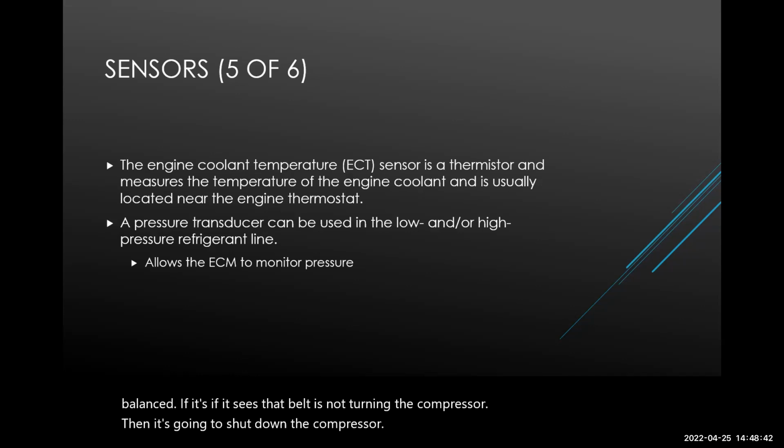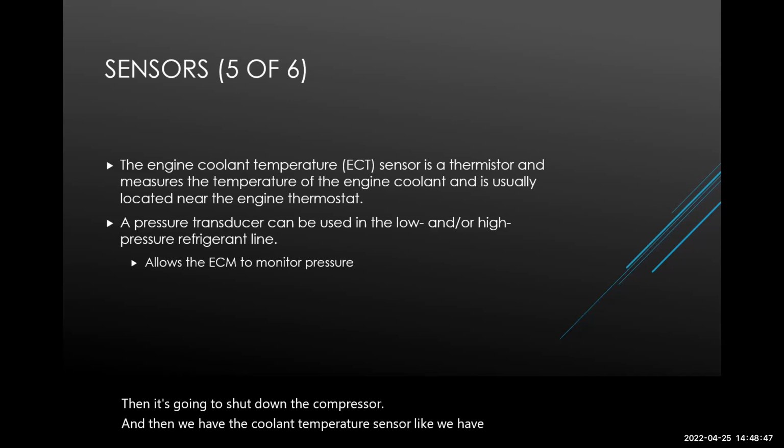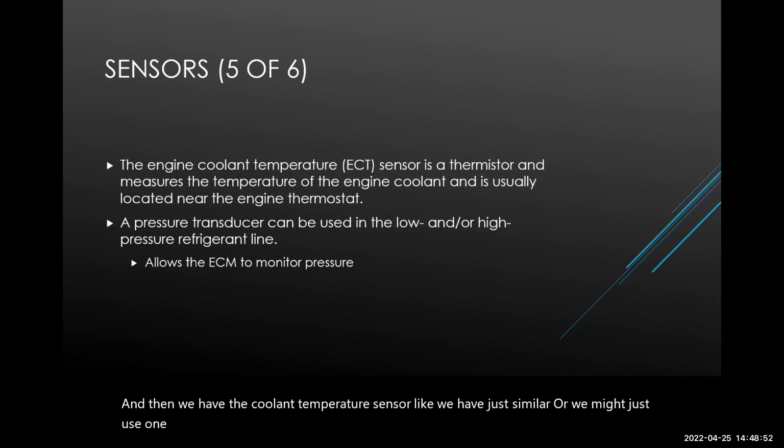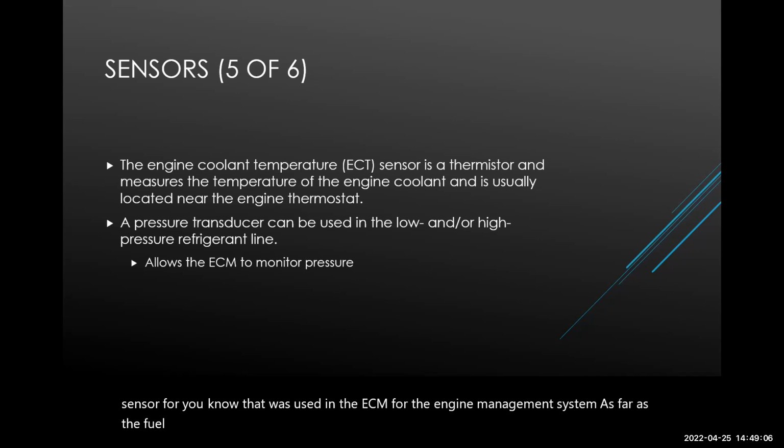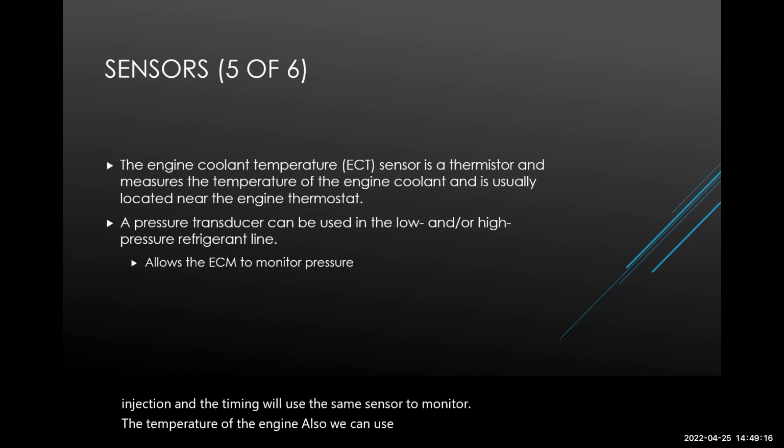And then we have the coolant temperature sensor, or we might just use one, especially on your network systems, where we borrow the temperature sensor that was used in the ECM for the engine management system, as far as the fuel injection and the timing. We'll use the same sensor to monitor the temperature of the engine. Also, we can use this in several ways.